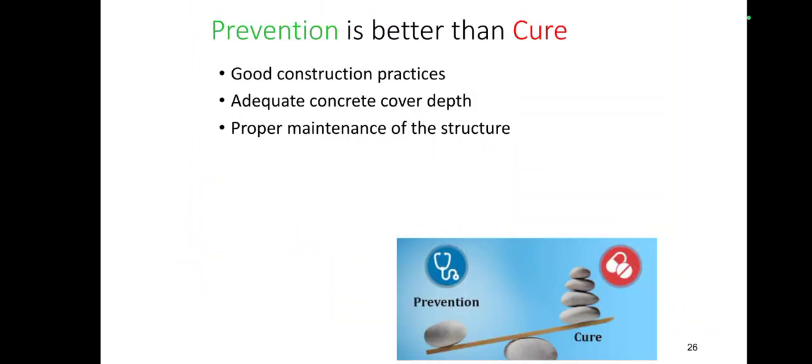Before closing, the important quote: prevention is better than cure. When you do the construction, if you follow proper cover depth, use this type of inhibitors and proper workmanship, if we follow good concreting practice, we can prevent this type of failures.